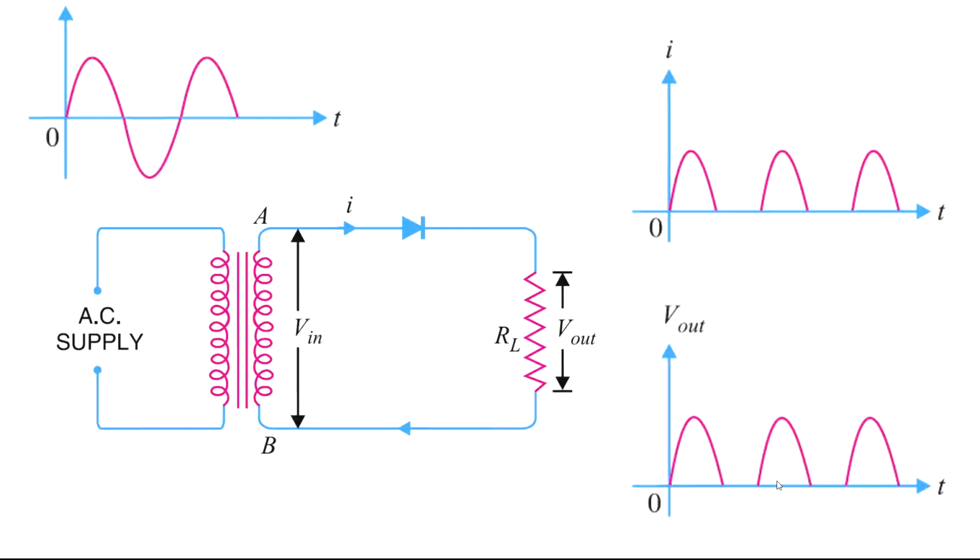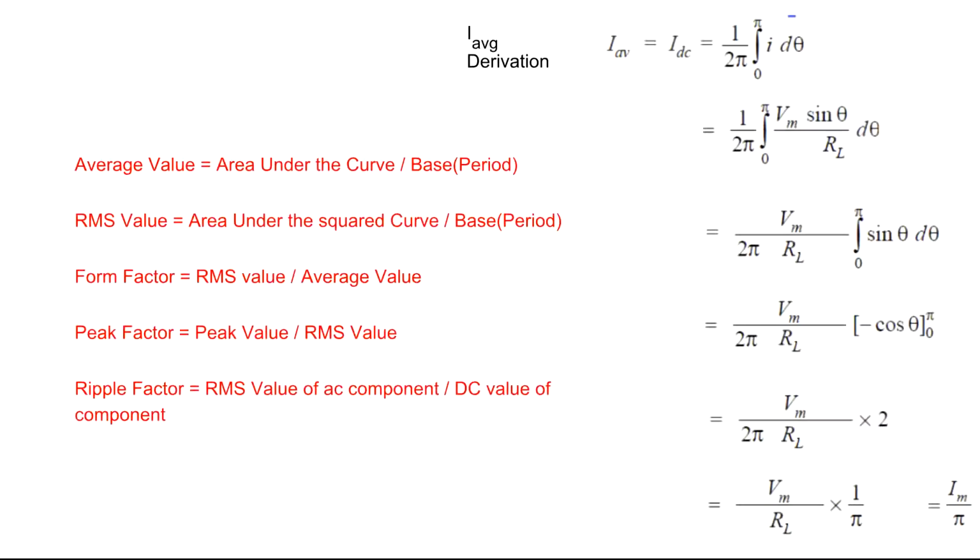If you understand this clearly, the half wave rectifier circuit, the output current waveforms, the Irms current, and average current, deriving those values, then that is the fundamental basis to go further into the bridge rectifier related circuits and their related calculations, and fully controlled SCR based rectifier calculations that will be used. Okay, so here you find this.